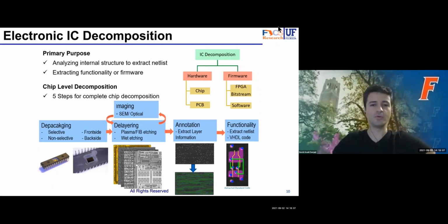So this destructive approach on the ICs is basically opening up the chip, getting rid of the package, going into the die, polishing the die down to the circuit level, and looking into the polys and the dopings and the connectivity of these transistors and gates, and from there, looking for possible Trojans. These Trojans can be a change of the doping, for that matter. They can be a reroute. There can be a different gate installed or fabricated somewhere it shouldn't be, an AND gate replaced with another gate, and so on and so on.